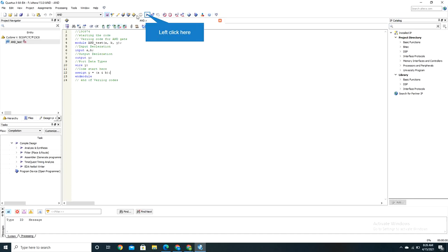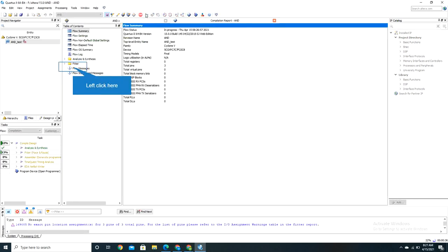We will simply press run on the circuit. It will take a few moments and then it will run. If any error is produced, you should circle it and cancel it out. So how can we remove the errors? The most common error is that the name of the file you have written is not the same as the name of the file for the AND gate, and it will not produce the circuit.